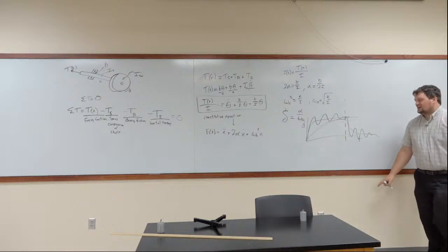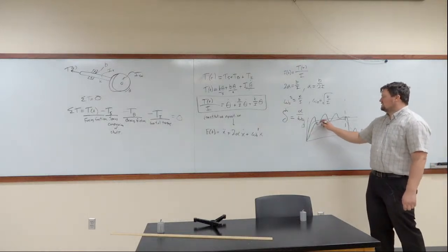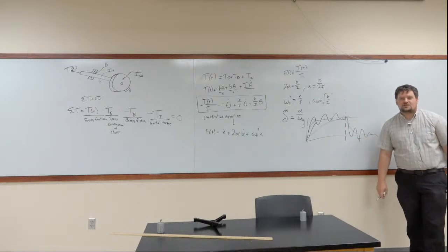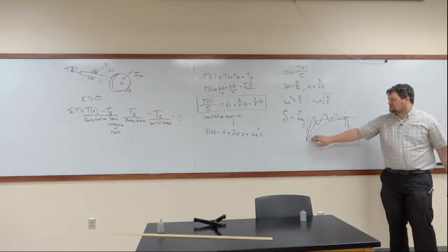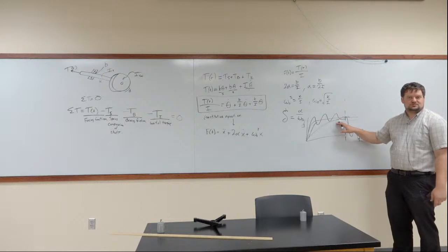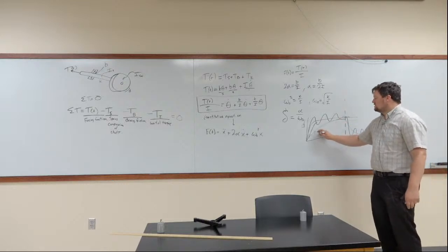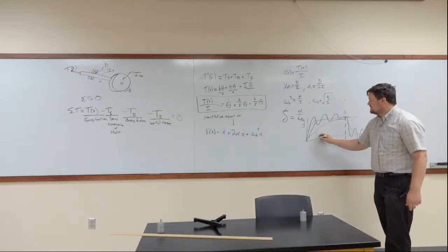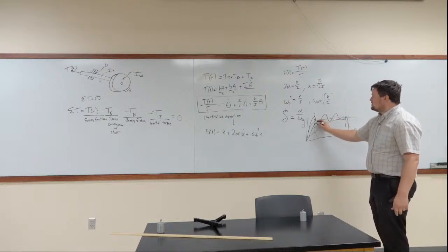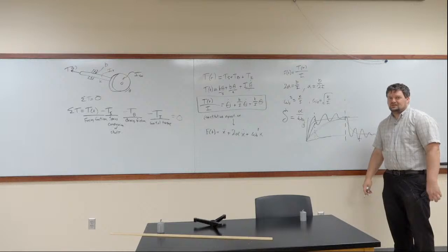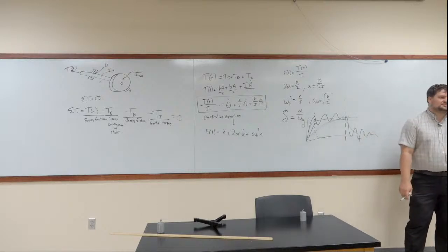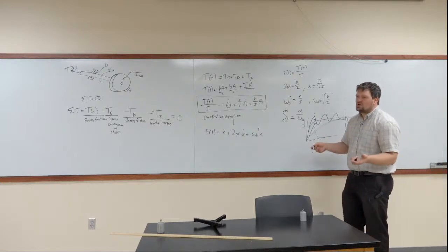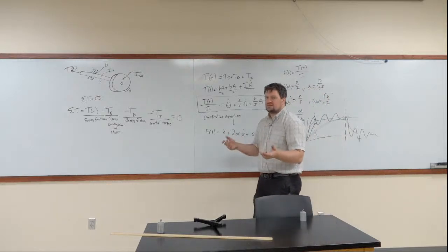That is an underdamped system. A critically damped system would give you a bigger jolt than an overdamped system. An overdamped system would feel more cushy. As you'll notice, you don't accelerate upwards as much. So here, if the bump is really small, you only reach here before you are already going back down. In a critically damped system, at that same point, for the same bump, you're already almost at equilibrium. So vehicle suspensions try to go with an overdamped system because you feel them less. It assumes that most of the interruptions you're going to see are very small bumps, and as a result, it tries to filter them out.